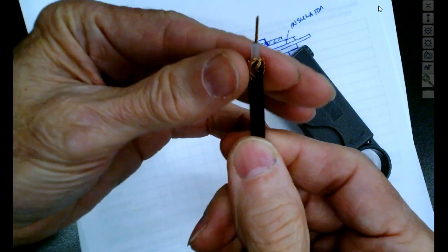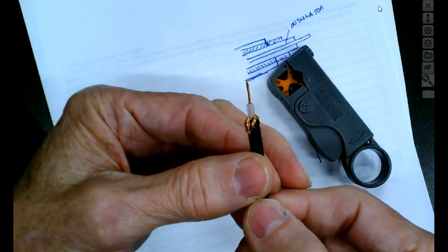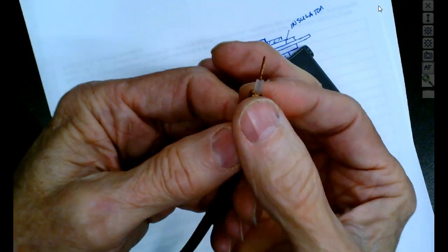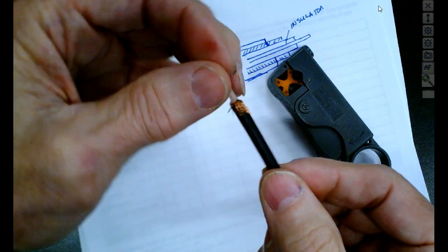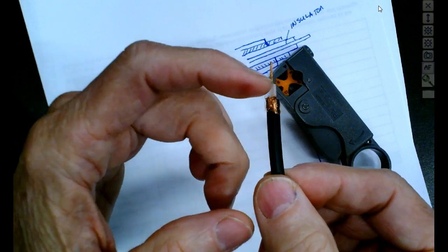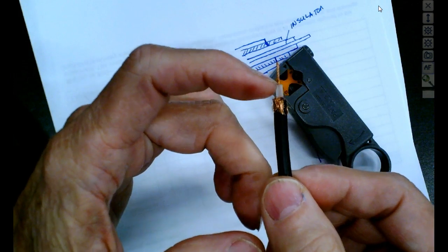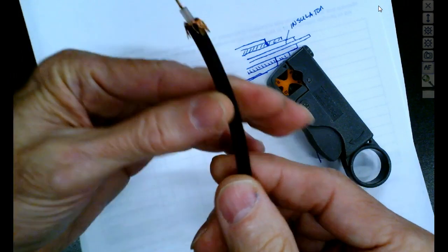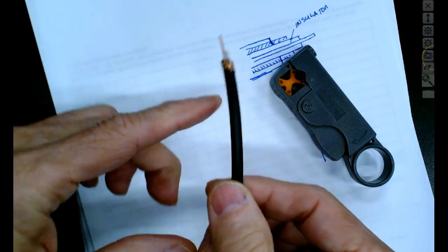They have tools that automatically crimp this on, and we'll show y'all some of that. But this is a typical coaxial cable. And of course, we have to maintain the spacing. So later on, when we look at how to terminate this, we'll see the connectors and how we maintain this precise distance between the inside conductor and the outside conductor, and we keep the insulation at the same thickness, and that's what sets up the capacitor. So this is a typical coaxial cable, single strand coaxial cable.